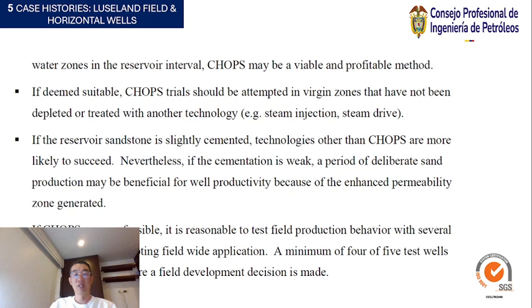If CHOPS appears feasible, it is reasonable to test field production behavior with several pilot wells before adopting field-wide application. A minimum of 4 or 5 test wells seems reasonable before a field development decision is made.